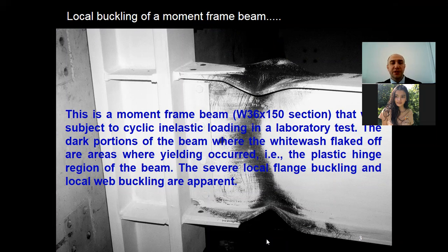On the picture you see the beam section. This beam section was seismically compact. Note that being seismically compact does not actually mean local buckling is prevented. It's not actually possible to prevent local buckling in general. Local buckling can only be delayed. So this specimen developed the full plastic flexural strength of the beam and maintained the strength through large inelastic deformation.